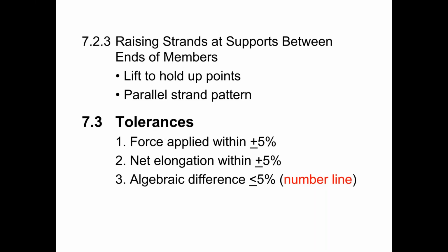Whereas if the strands are not parallel, which would be the case if we have a draped strand double T, where the strands were tensioned initially straight, and then they were pushed down into the draped position. So they started out in the straight position where they were a couple of inches apart from each other, or some other nominal value.